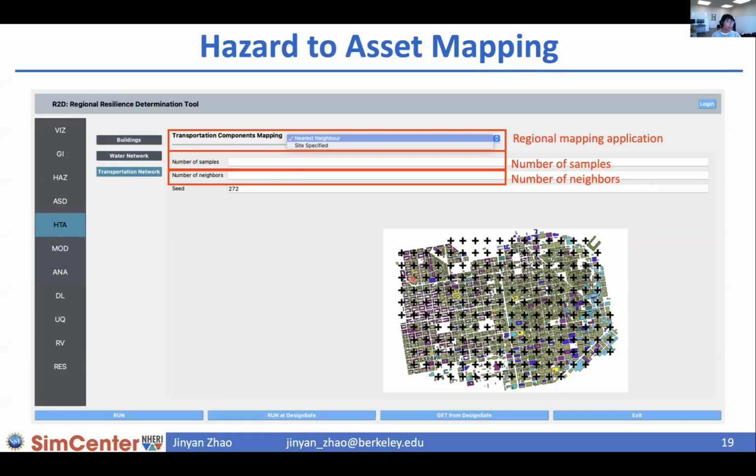And also, very likely the ground motion under two buildings close to each other are almost the same. So you are just wasting some space and computational resources. So a more common way is to define the ground motion on a coarser grid field, like these black crosses. And then you can use this nearest neighbor algorithm to interpolate between the grid points to get the ground motion value at a building between the grid points. This nearest neighbor algorithm is almost equivalent to a weighted interpolation between grid points, and you can find the details of the algorithm on our web page in our documentation.